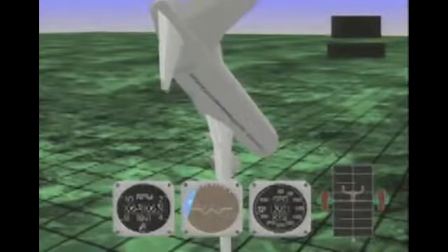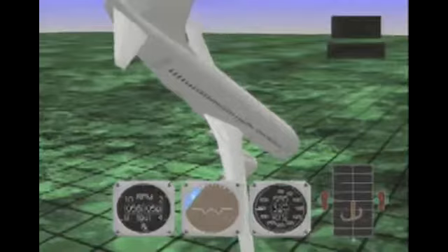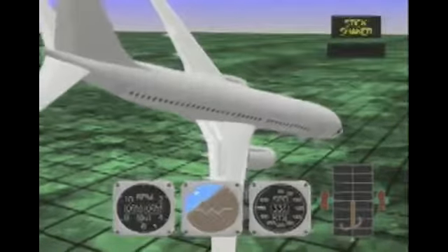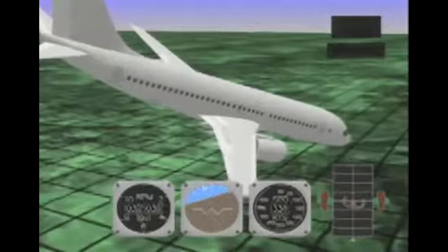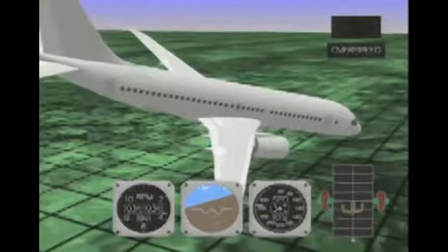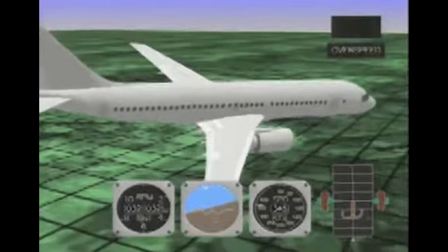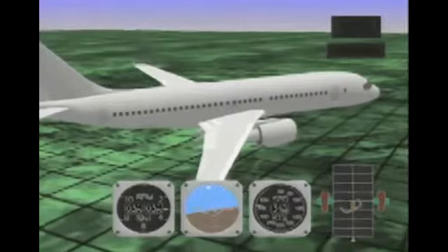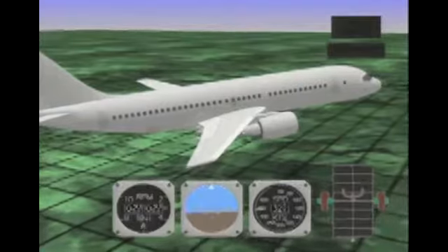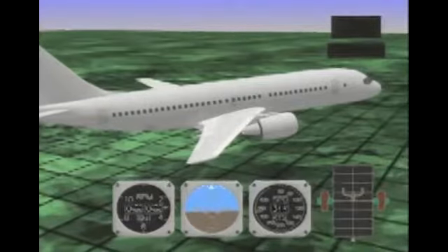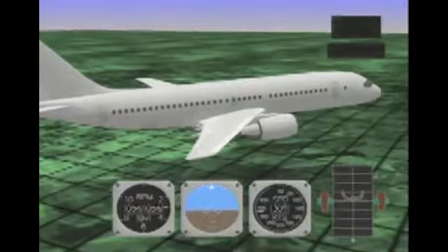In this situation, it may be necessary to unload the airplane by decreasing back pressure or even pushing to obtain forward elevator pressure. Use full aileron and spoiler input if necessary to smoothly establish a recovery roll rate toward the nearest horizon. It is important to not increase G-force or use nose-up elevator or stabilizer until approaching wings level.